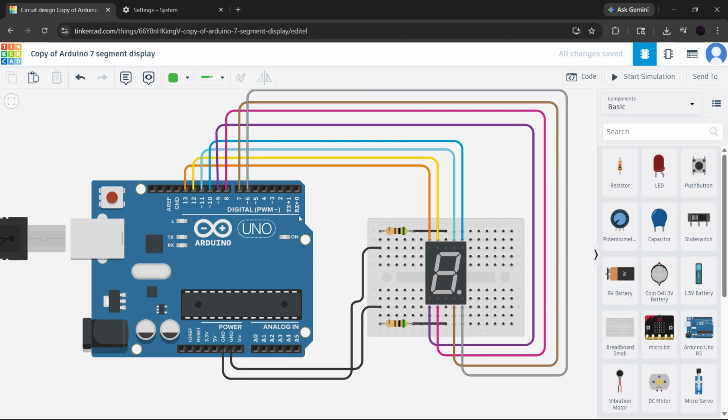Next, let's look at stuck component scripts. Some complex parts in Tinkercad, like the 7-segment display or LCD modules, rely on custom background processes. Sometimes those scripts get stuck, and the simulation fails even if your wiring looks okay. In that case, the simplest fix is to delete the complex component and drag in a fresh one from the side panel. That resets the part and often clears the issue immediately.